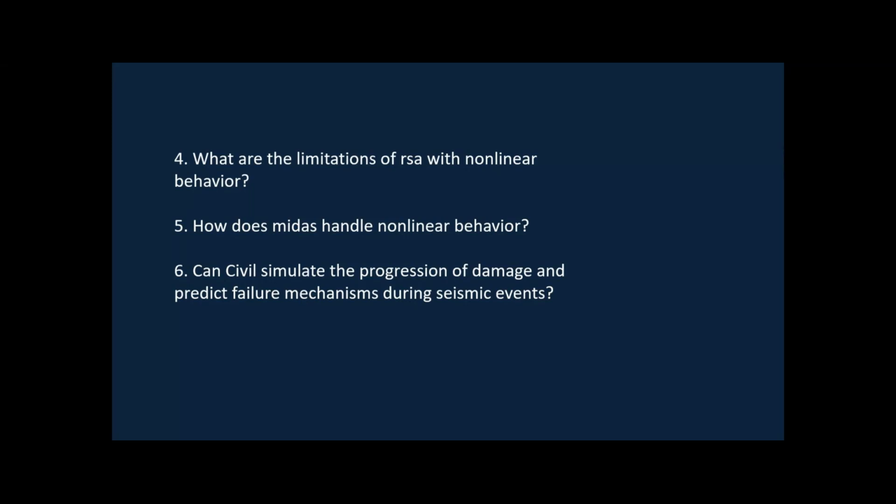It will only be an estimate of the displacement, because we are only catering for the seismic criteria with the help of the response reduction factor and nothing else. Thus, response spectrum analysis does not cater for any nonlinear behavior.